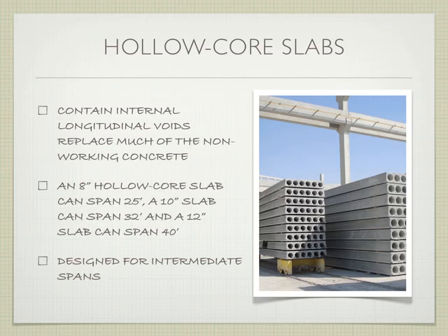An 8-inch hollow core slab can span 25 feet. Right? So we're starting to get further distances. A 12-inch slab can span 40 feet. Right? So we got much further distance out of the depth. Make sense? Okay? They're designed for the intermediate span category.